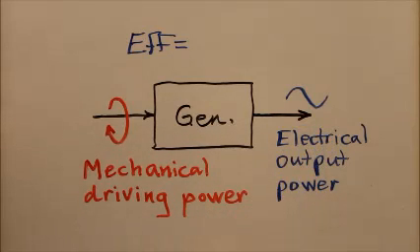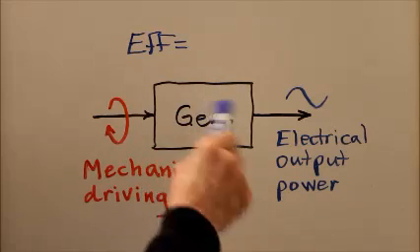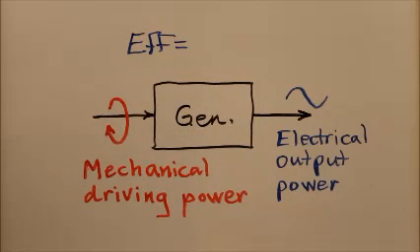Generally speaking, the more that we demand out of the generator in terms of power, the more mechanical drive we're going to need. You don't get something for nothing. If you have an electric generator and the output isn't connected to any load at all, like nothing is plugged into it, it doesn't take very much driving power to make that device work. It's actually like a motor in reverse.